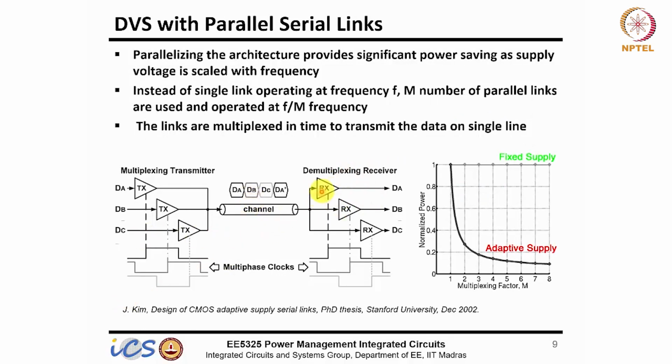This is the thing they use, and I think it's nothing but muxing. They try to change the number of parallel transmitters they are using. So for normalized power, again they change the multiplexing factor. They increase the multiplexing factor when operating at a higher load, and when the load reduces they reduce the multiplexing factor. It's like using multiple phases, just like we saw in the LDO, and you keep turning off the phases as your load reduces. So they are using a similar concept.